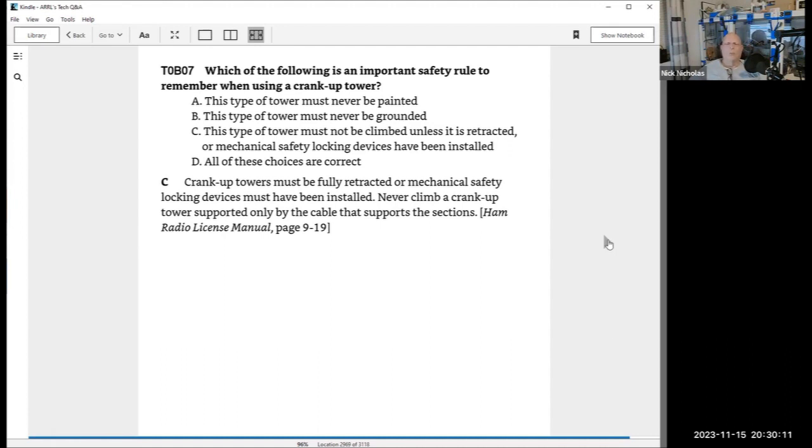If the tower gives way as you're climbing up, each section inside the other will collapse down, and whatever you're holding on to, the section above it will act as a guillotine and cut your fingers and toes off on its way down. And guess what happens to you? Even if your safety harness and lanyard break your fall, you might bleed out before they get you down. Sound like a good reason not to climb one?